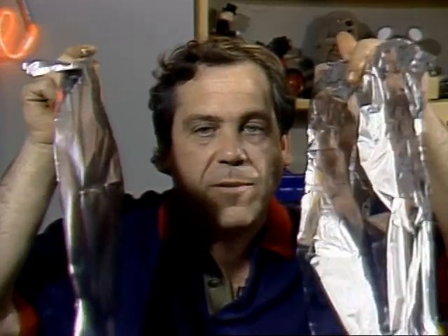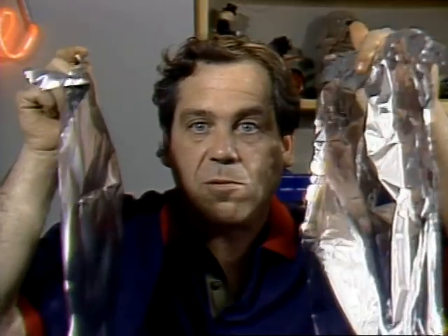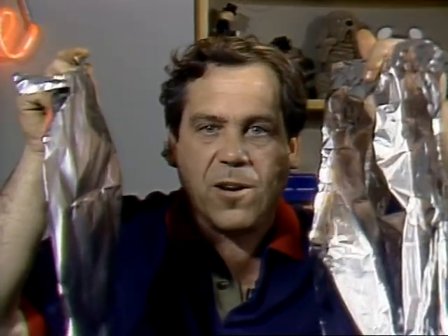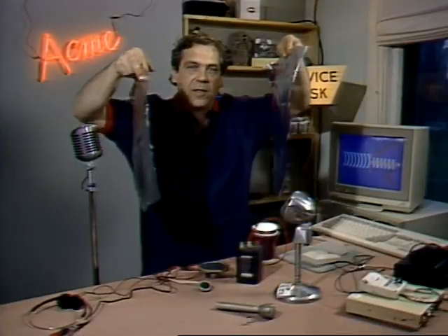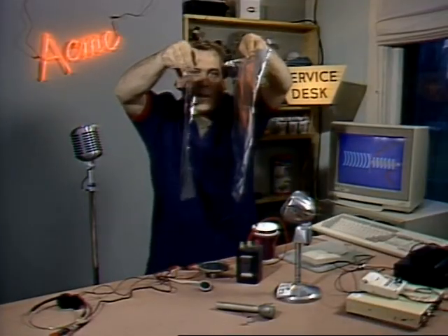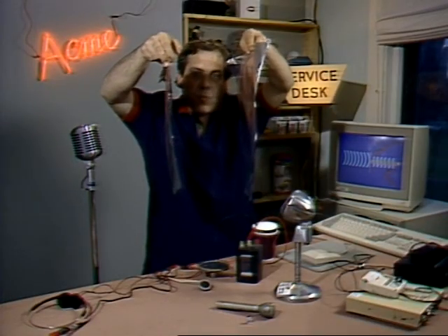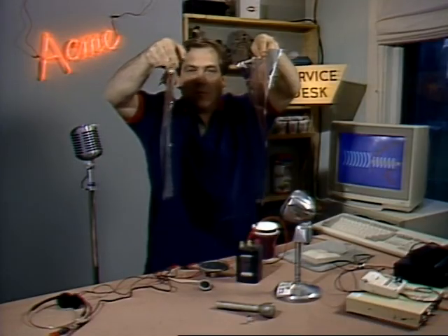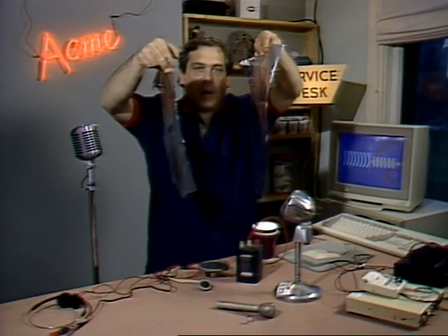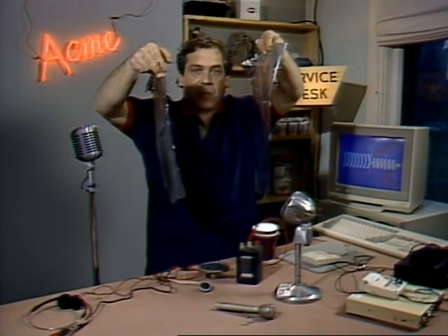Early condenser microphones used a 400-volt power supply to polarize the plates. The supply was the size of a loaf of bread, and the sheets were, well, a little smaller than this, but not much. Sound pressure fluctuations wobble the gap, and the wobbling electric currents can be detected. The only work that the sound waves do is to move the diaphragm. The electrons and the power supply do the rest.